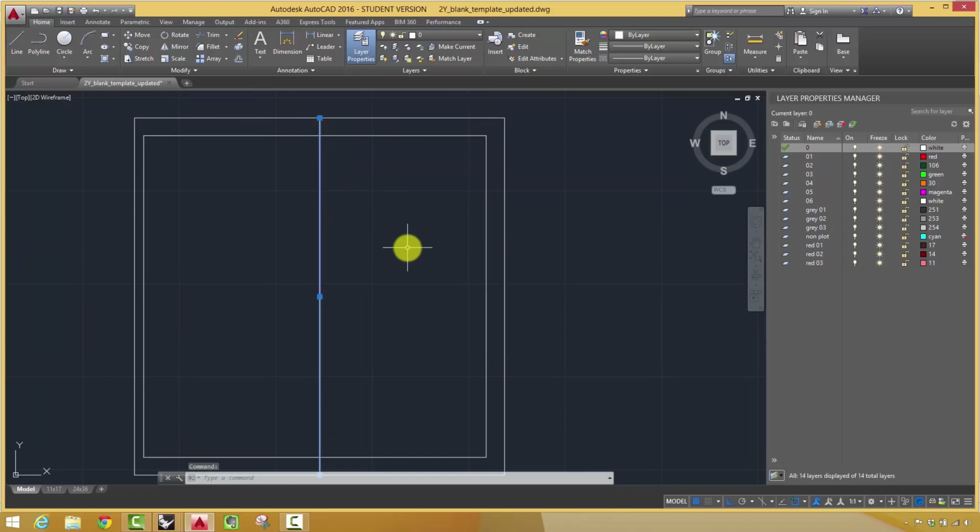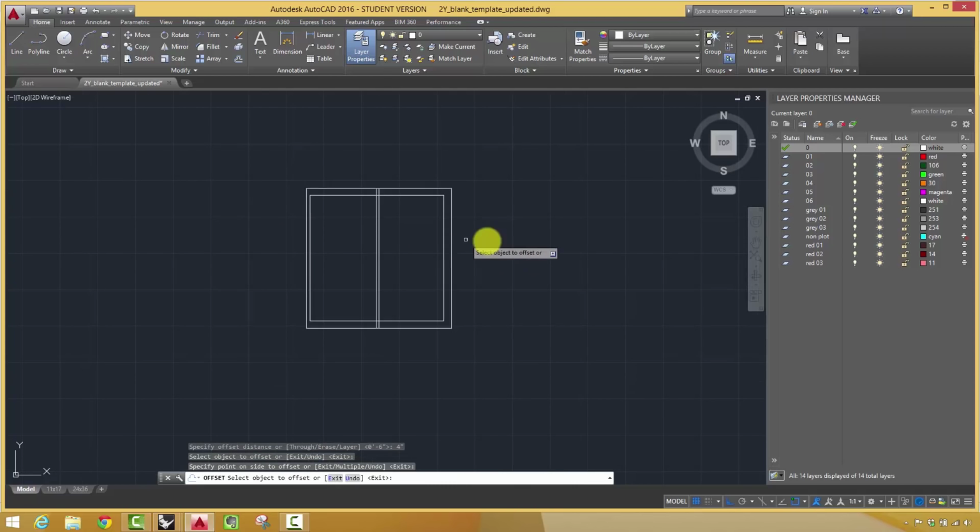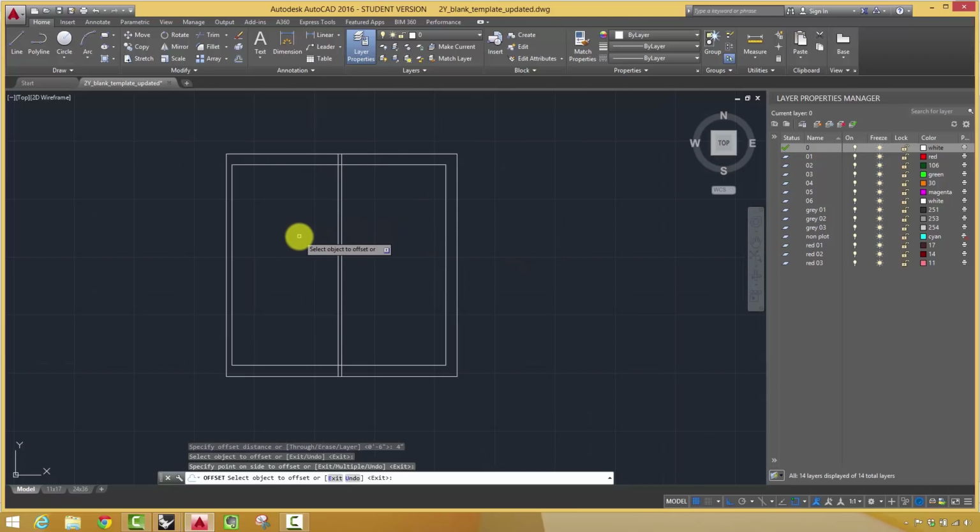We're dealing with center lines, and the center line is important because basically it means that whatever object you're creating, whether it's a partition or a window or a door, is on center. You don't typically go from edge to edge because you want things to fall on a grid. You want things to fall on guidelines, right? And there's a difference. Let me just show you the difference here. 4 inches offset. I think you understand there's a difference between that, right, which actually slightly favors this side, and actually doing it on center.